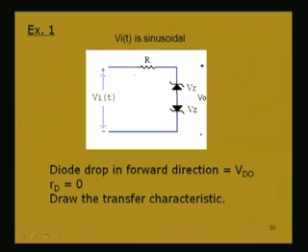So, if you give a sinusoidal voltage, you can find what will be the output. Now, whenever the input voltage is in the positive half cycle, this Zener diode will be reverse biased, but the other diode will be acting like a normal diode when this point is positive with respect to this point in the positive half cycle. But when the voltage at these 2 points is greater than the whole voltage drop across these 2 points, that voltage drop is Vz plus Vd naught.